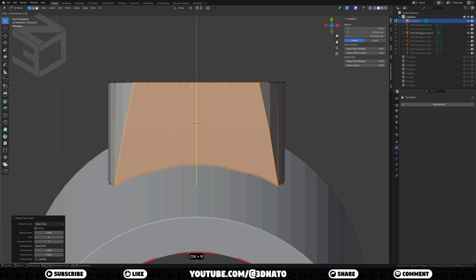Press Ctrl plus R to create a loop cut, type 9 and enter 2 times to confirm. For the Boolean modifier to work properly, we're going to need 2 things. The first one is to move this bottom edge loop a bit inside the hand, and the second one is to fill a face on this loop.